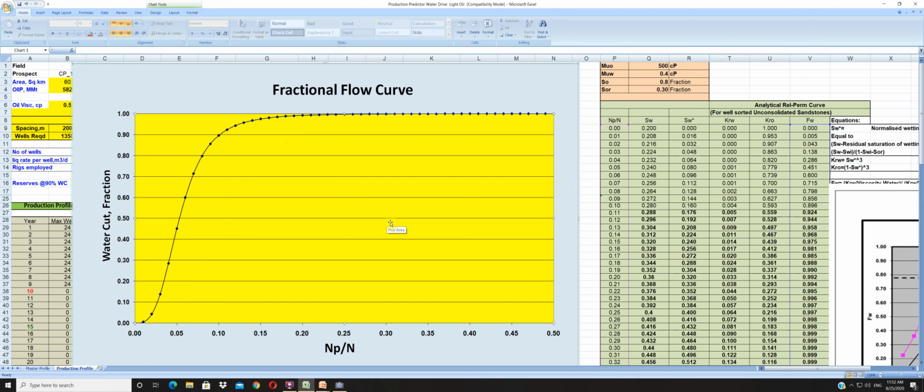Now, if we go to the heavy oil regime of around 500 centipoise, the fractional flow curve shifts to the left. That means at 90% breakthrough, we get a very low recovery of around 7 to 10%. This is not a rosy picture at all. So what happens? From day one, that's what I said, some of the EOR processes have come out of the tertiary EOR bank. They have come right at the primary stage.